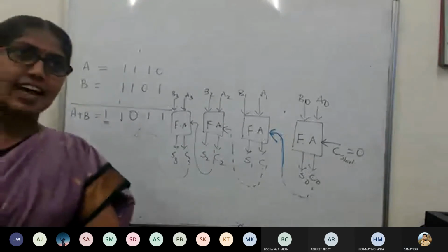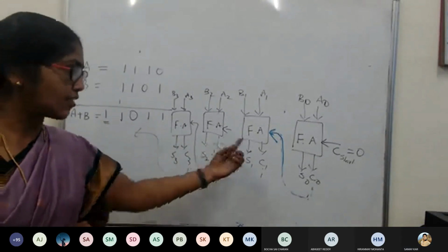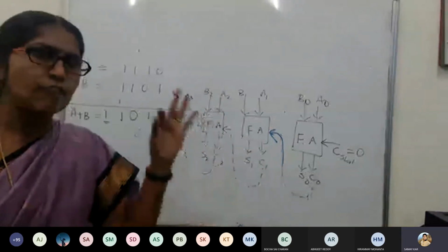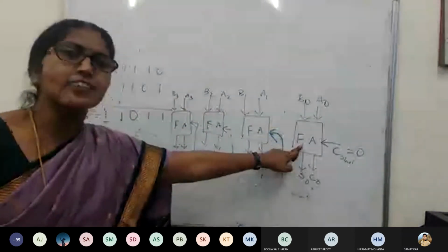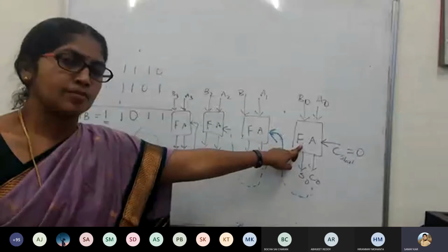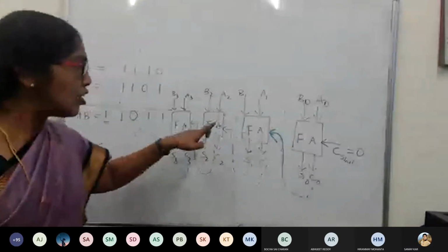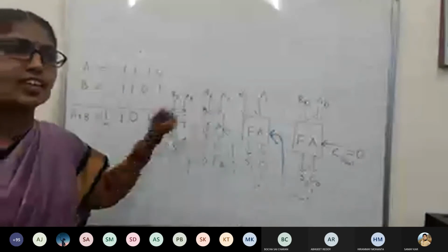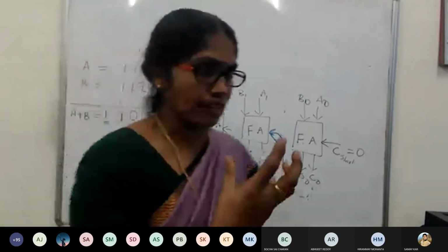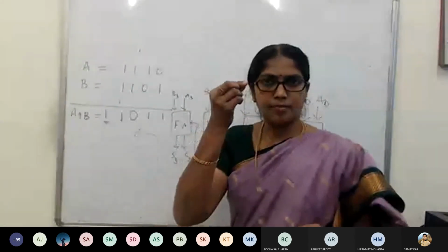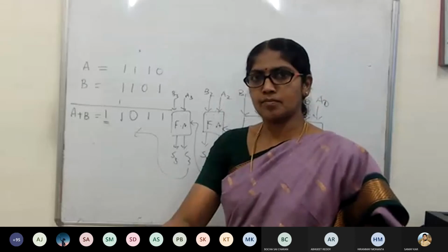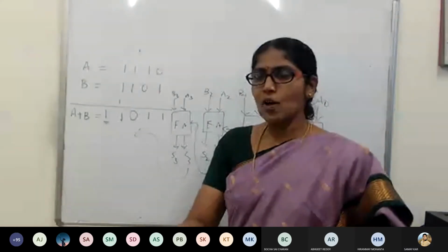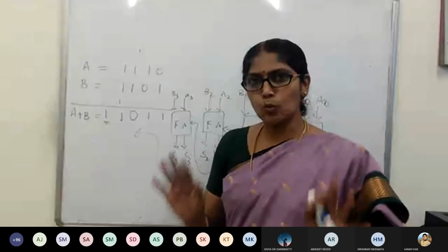Now, can I say that in order to make this full adder work, it has to wait for some time for this carry to be generated? Yes, ma'am. Similarly, in order to work this one, it has to wait till this carry is generated. So you can expect a delay in our outputs, right? Right, ma'am. So now we have no option other than waiting.